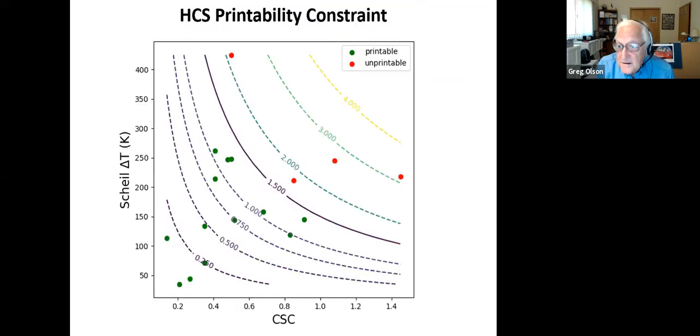So along the way, to constrain materials for resistance to cracking during printing, we have developed a combined cracking resistance parameter that combines the parameter that has been developed by the casting industry for resistance to hot tearing, and combine that with the freezing range, which comes from the welding technology to constrain against welding fracture. And that combined parameter has then allowed us to constrain compositions against those cracking mechanisms. As well, there is another criterion on the quench suppressibility of precipitation strengthening in these alloys. So that's given us the constraints to design specifically for the process.